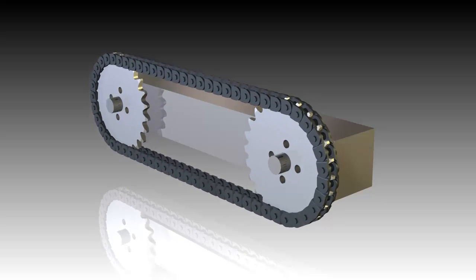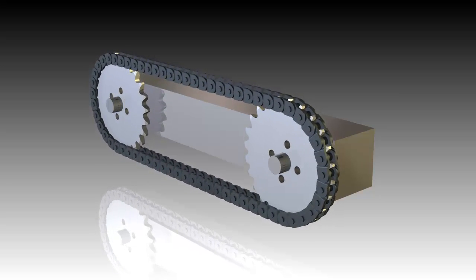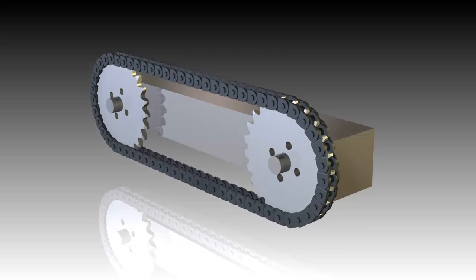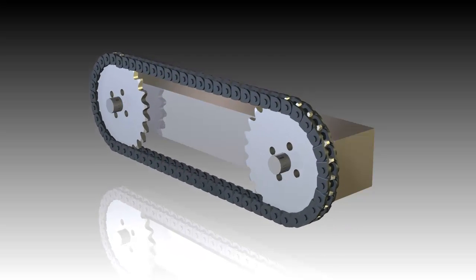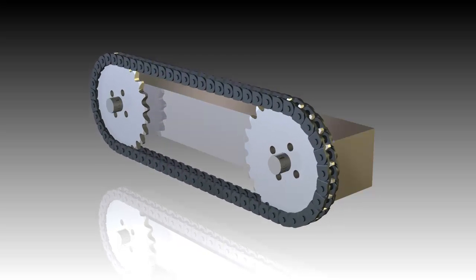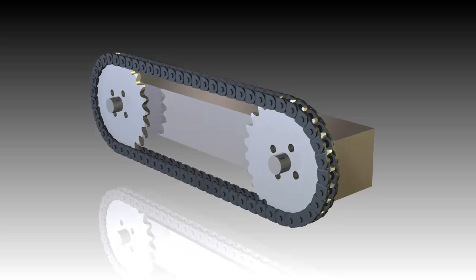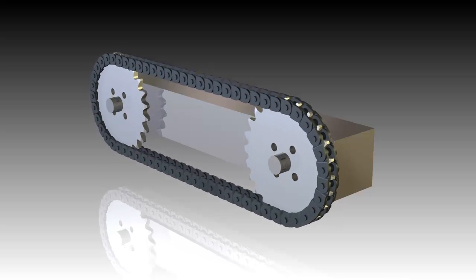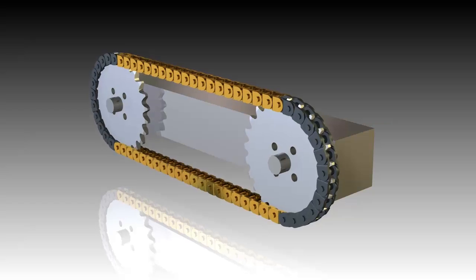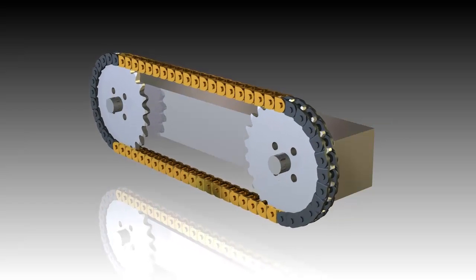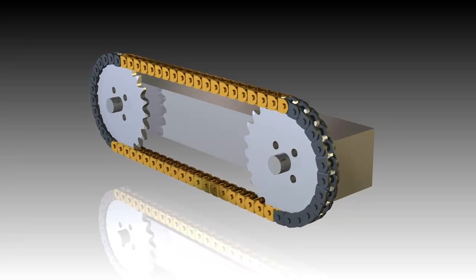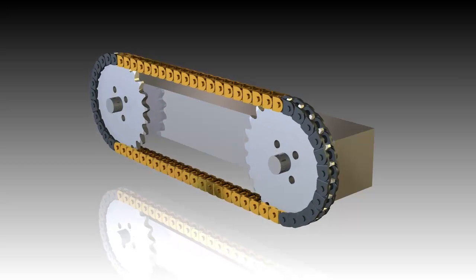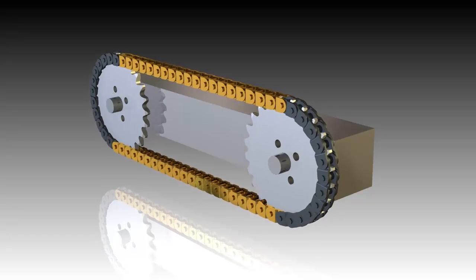But before we get started, there are a few tricks we use when modeling chains that are important to be aware of. Instead of full links, we use half links. We do this because of the shorter dimension between repeating elements. Another trick we use is that the links don't travel all the way around like it appears in this animation. Instead, two straight segments and two curved segments only travel a certain angle, then reset themselves to their initial positions. This is accomplished through functions that we will get into later.